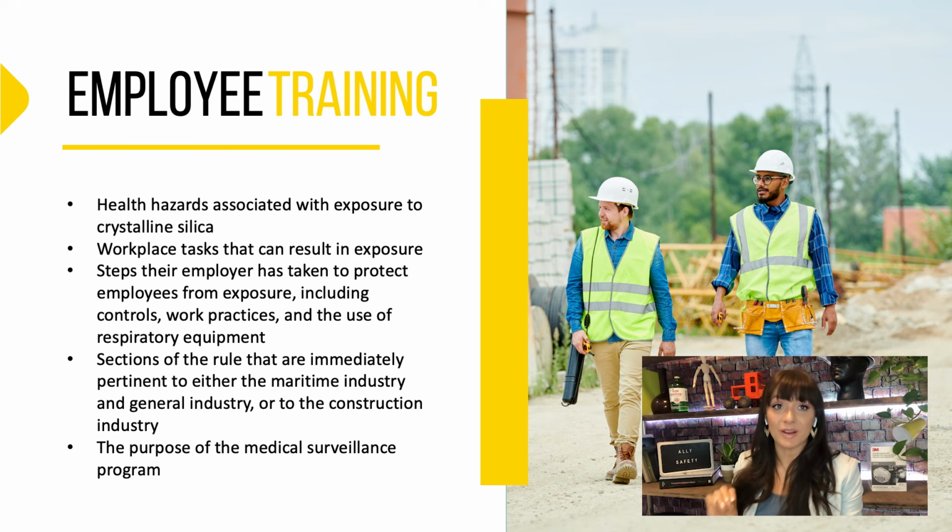Employees need to know about the hazards associated with exposure to respirable silica, and they need to be able to take steps that can protect themselves, like we talked about engineering controls, work practice controls, PPE. Having a good training program that really helps employees to understand what they can do to protect themselves and why they should is a really key component in all of this. People do better when they know better, and so if they've been trained, they'll understand why it's important.